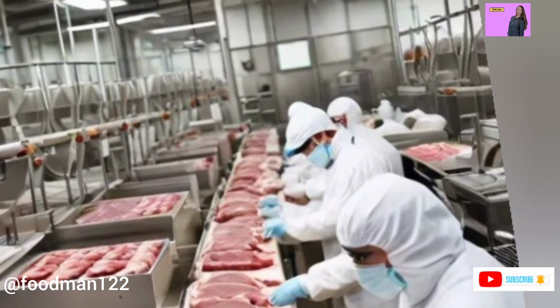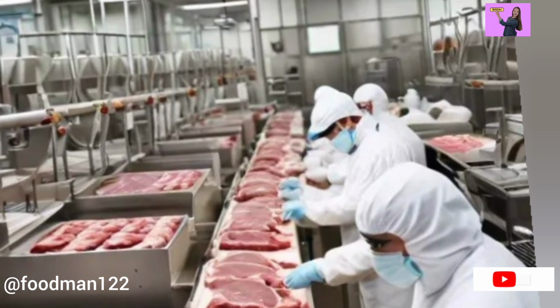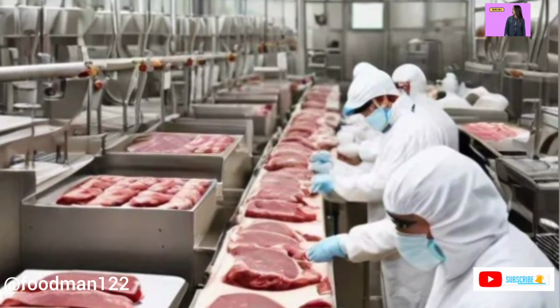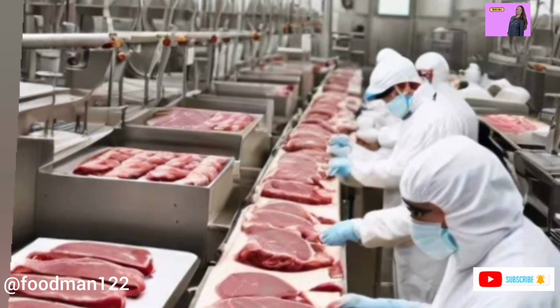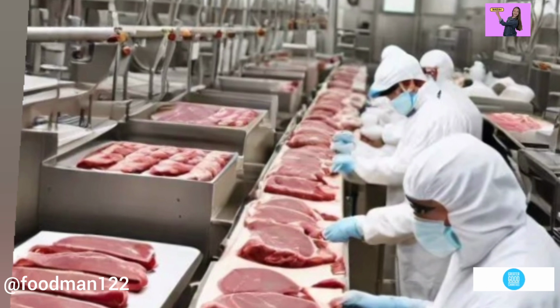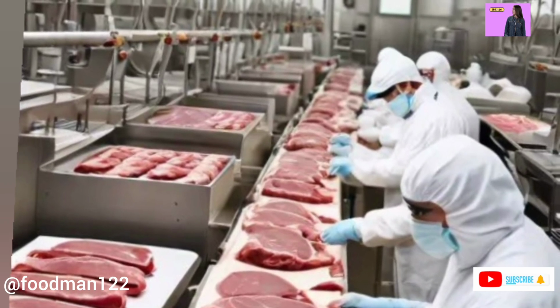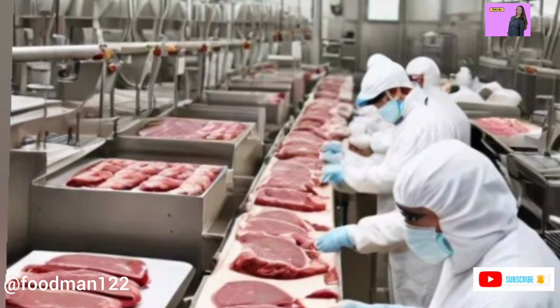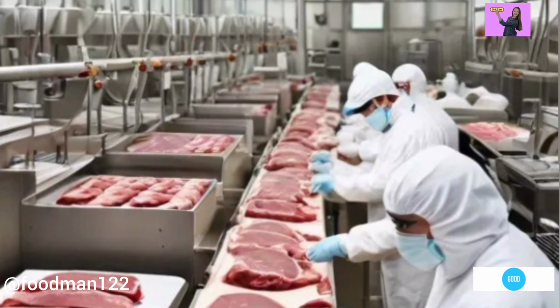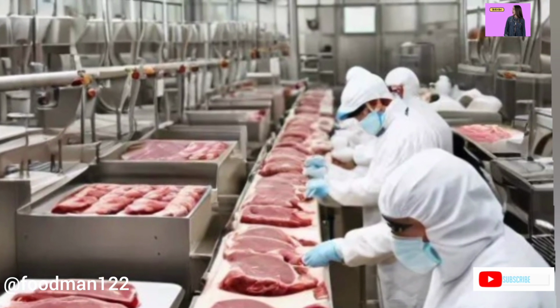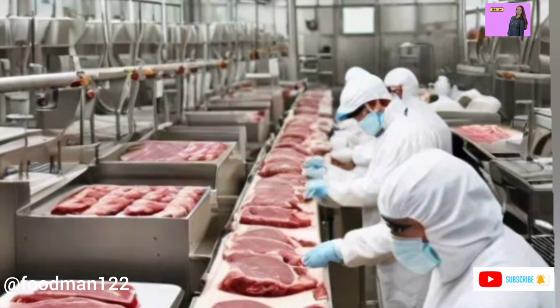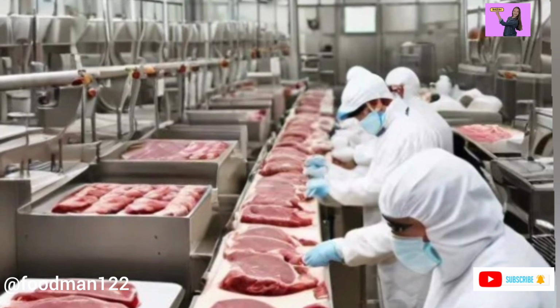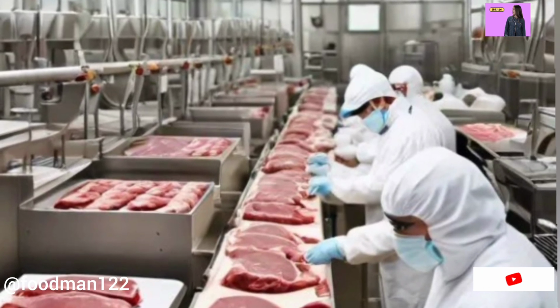Construct a flow diagram. Map out each step of your process, from raw material intake to final product storage. Conduct hazard analysis and identify CCPs. Apply the first 2 principles of HACCP to your process and set critical control points. Implement monitoring and corrective action procedures. Develop specific protocols for monitoring CCPs and outlining corrective actions when limits are breached.